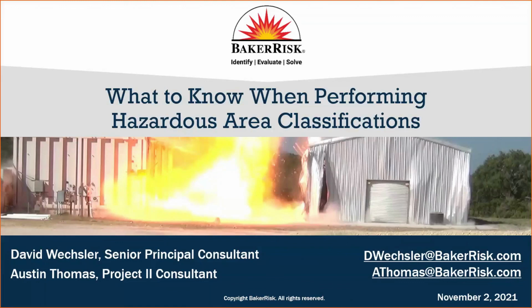So for example, if we have a process and we determine that the process leakage coming out into the air is unlikely under normal conditions, but it could happen, then we might have a localized leak as opposed to a condition where we say we are leaking material all the time and it's all over the place. That may have a larger extent distance. But again, for the scenario based upon how far the process leak or release can go, then you're looking at a different qualification. You're looking at what is the impact of the leak on society, on operations, on adjacent properties, and other things. So I think you can appreciate the objectives are slightly different.